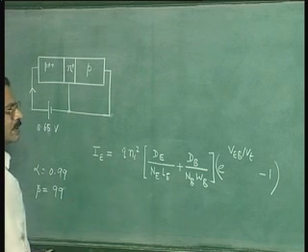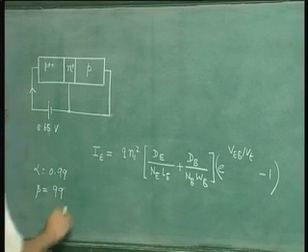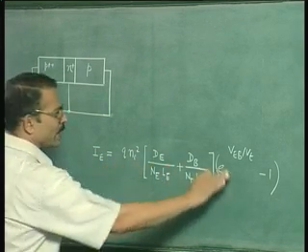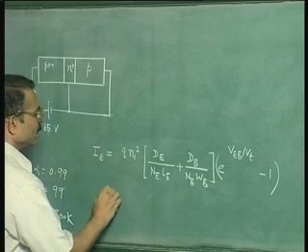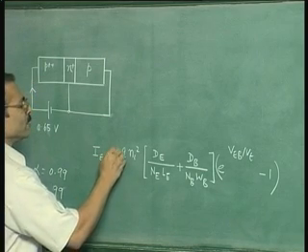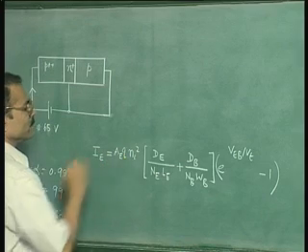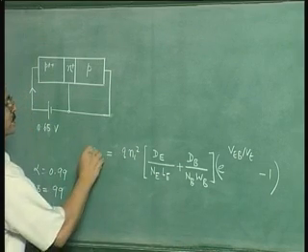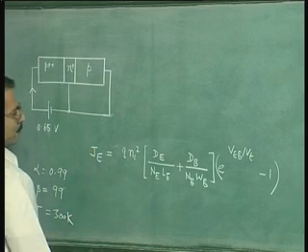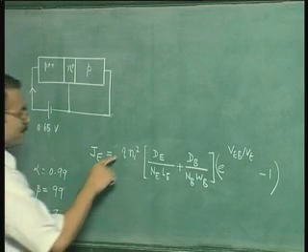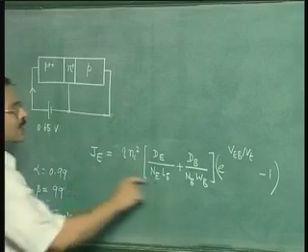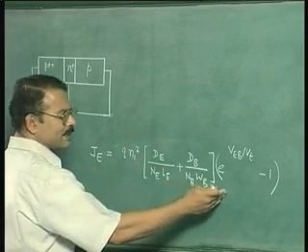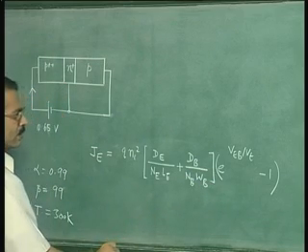We are discussing for T equal to 300 K. So if you calculate this, you will find, incidentally here we must also put the emitter area. Without the emitter area, this would be the current density. So one must never forget the emitter area. Without the emitter area, this is the current density. You can always do a dimensional analysis of this and check that the right hand side is amperes per centimeter square.